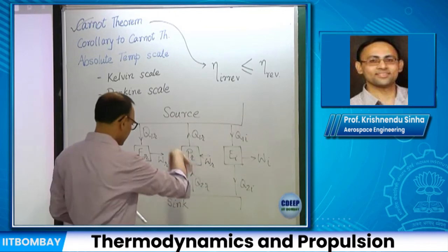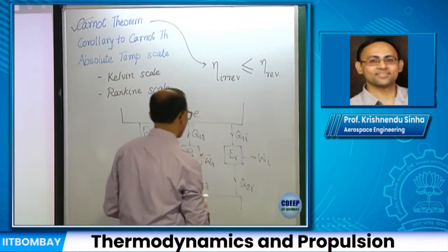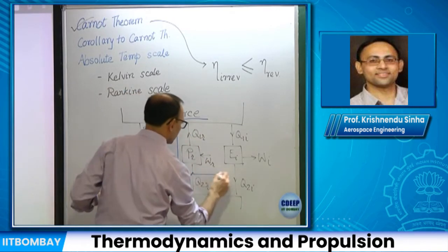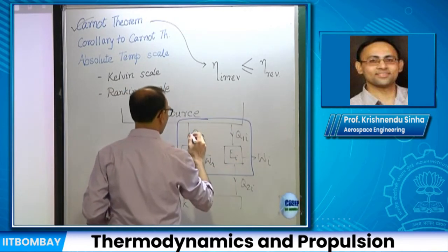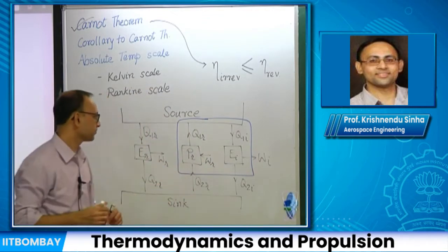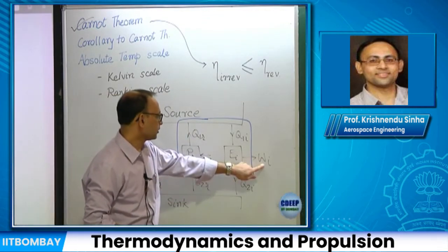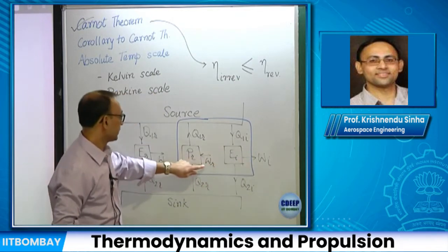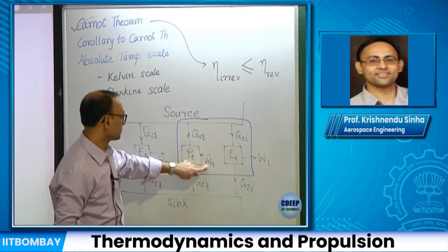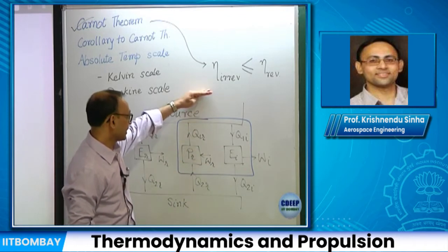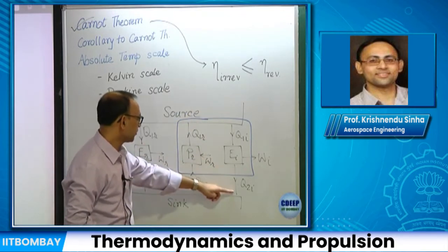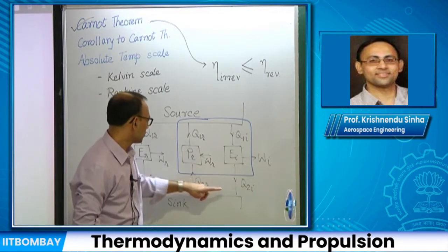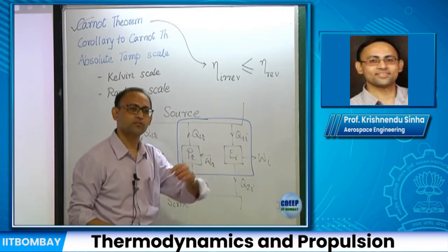Then we'll combine these two to make a new engine which will have a positive work output, because this work output is greater now, we are saying, than the work input of the pump. The top reservoir is eliminated, and the bottom reservoir gives us the net heat, which is Q2R minus Q2I. So you can refer to your notes last time.